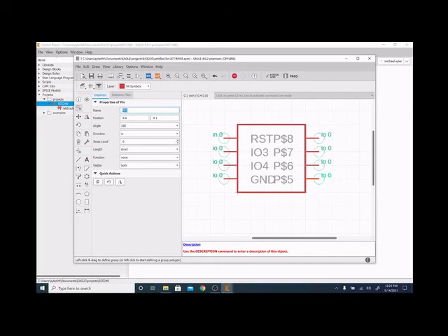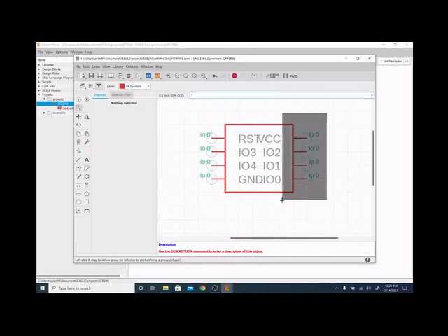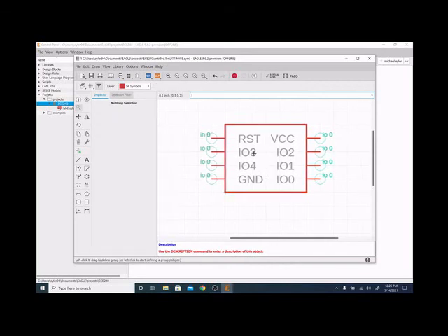This one is IO0. That could get a little confusing, so I'm not crazy about that indication, but it's just going to work. IO1, IO2, and finally VCC. That sounds good. All right. Okay, it looks like we're kind of stepping on each other's toes a bit here. So I'm going to do a box select over just this area, and it will take the text with it. There we go. All right, this does it for our schematic part for the ATtiny.